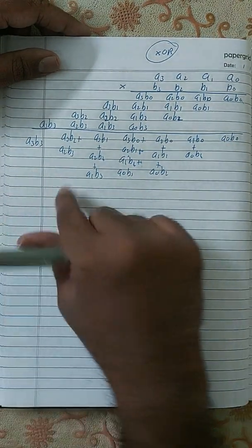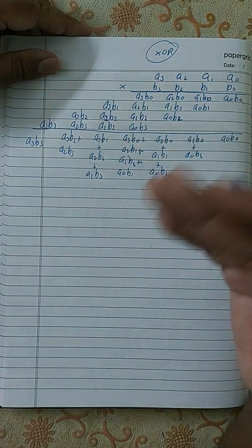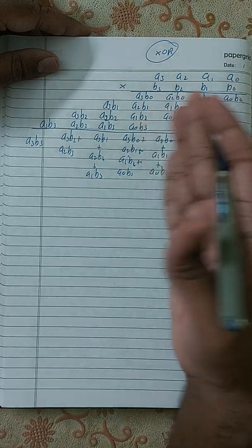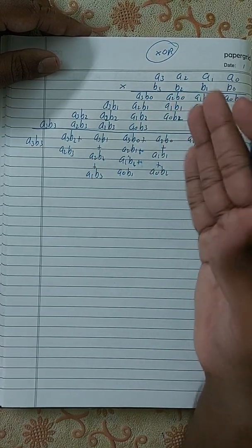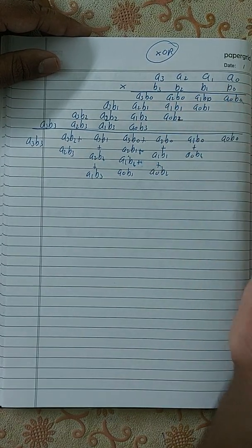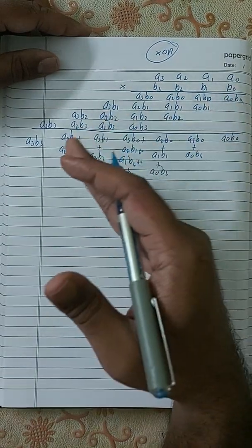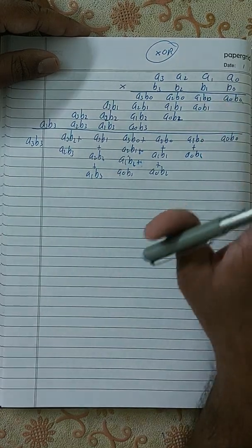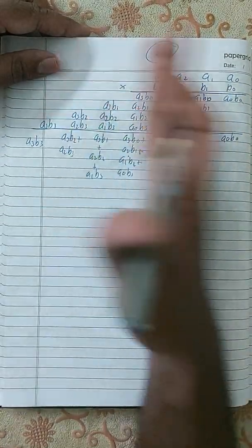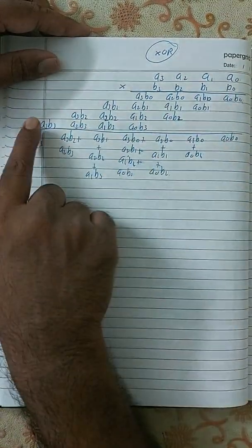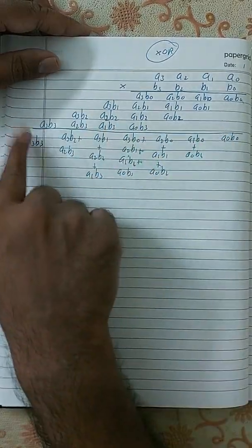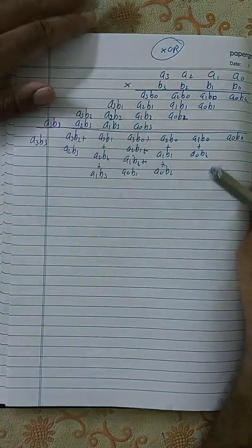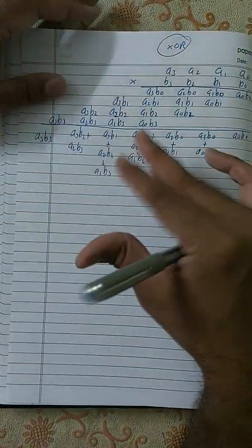Another interesting thing about this is there is no carry over here. You will never find a carry, because like I told you, this is nothing but a pure XOR operation. There is no half adder or full adder operation here. Only XOR operation, which means there won't be any carry. That means if you start adding from here or from here, you will get the same answer. That's another interesting aspect about this.